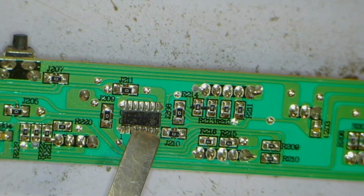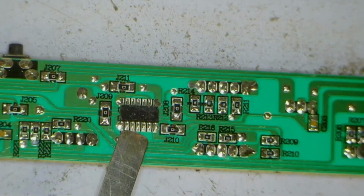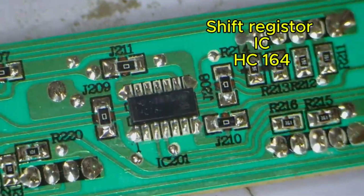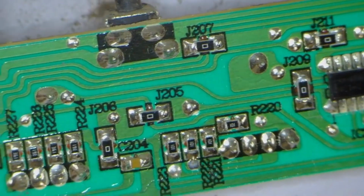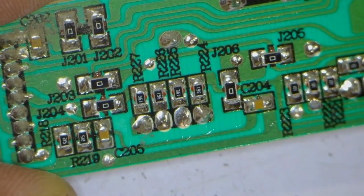This IC is responsible for turning the LEDs on and off. It's a 14-pin IC, and its part number is HC164. This is a shift register IC. If there's a fault in this IC, the LEDs won't work properly. I will also check the resistors in the circuit to see if any resistor is burned out. Looking at the circuit, no resistor seems to be physically damaged or burned.